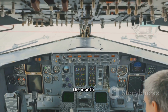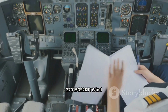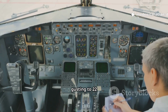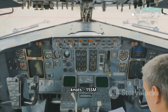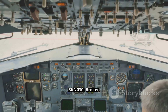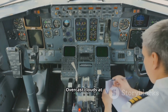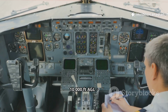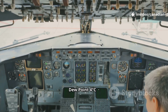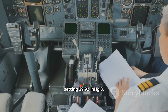041300Z: day 4th of the month, time 1300 UTC Zulu. 27015G22KT: wind from 270 degrees at 15 knots, gusting to 22 knots. 15SM: visibility 15 statute miles. BKN030: broken clouds at 3,000 feet AGL. OVC100: overcast clouds at 10,000 feet AGL. 12/04: temperature 12 degrees Celsius, dew point 4 degrees Celsius. A2992: altimeter setting 29.92 inHg.